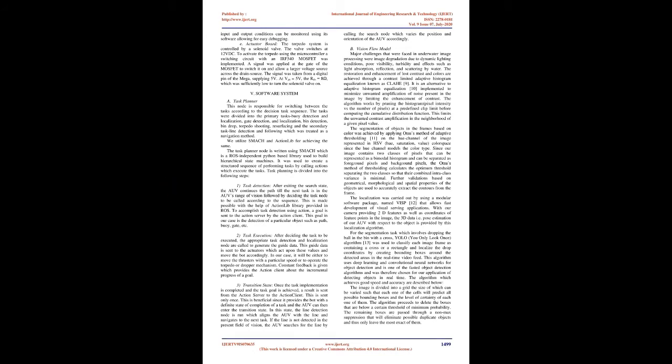2. Task execution. After deciding the task to be executed, the appropriate task detection and localization node are called to generate the guide data. This guide data is sent to the actuators, which act upon these values and move the bot accordingly. In our case, it will be either to move the thrusters with a particular speed or to operate the torpedo or dropper mechanism. Constant feedback is given, which provides the action client about the incremental progress of a goal.